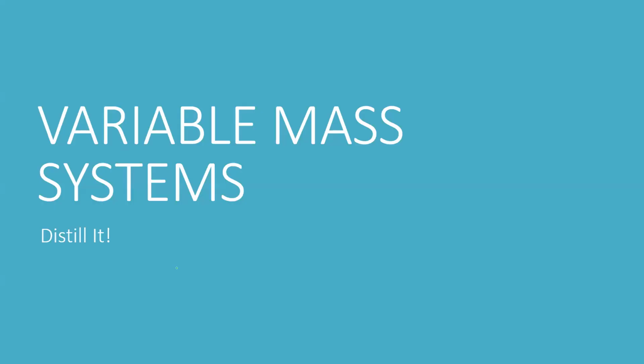Okay, so today we are going to talk about variable mass systems. So far we have considered all systems with a constant mass. We have said that we have a system, there is some amount of the substance present in the system. We are either heating it, or extracting work from it, or doing work on it, and that is increasing its internal energy or its enthalpy. Then we discussed pressure, temperature, and volume relations of this kind of a system, right?